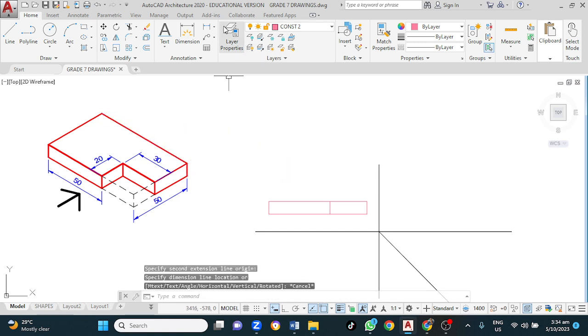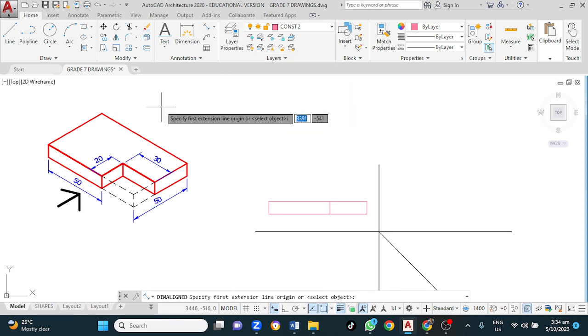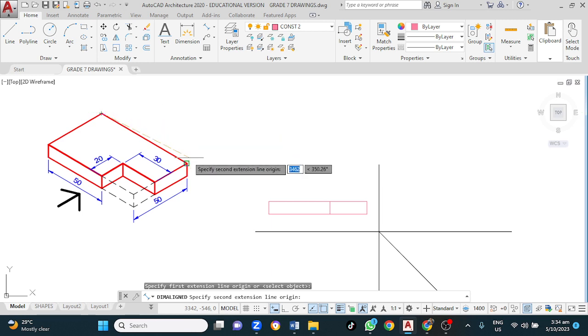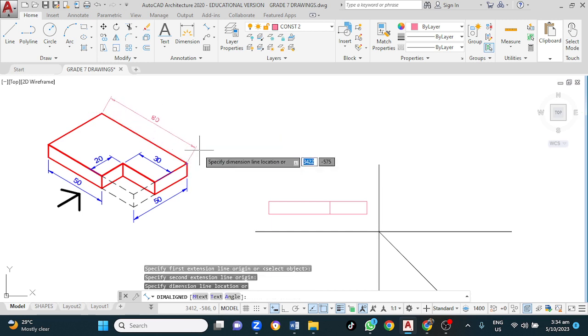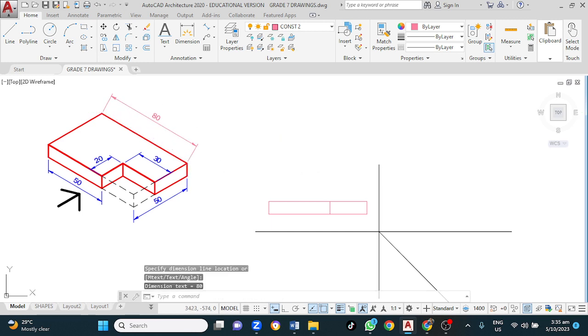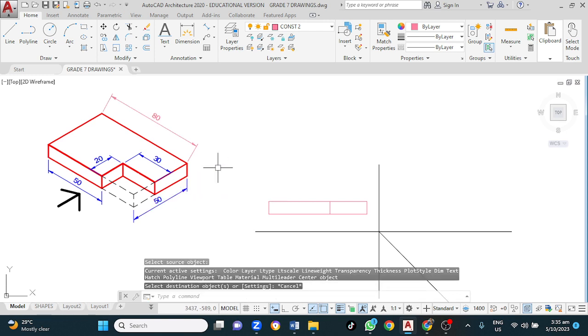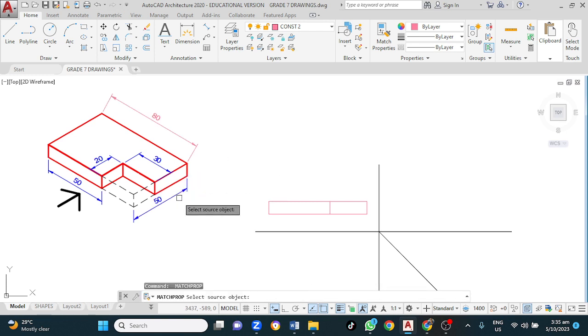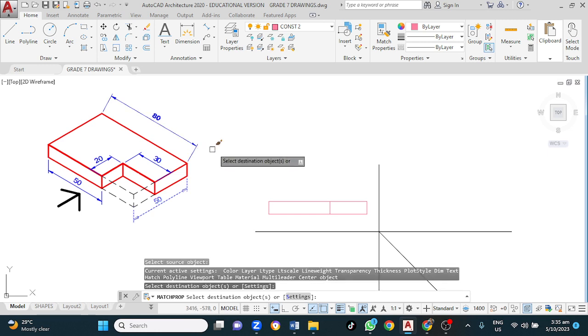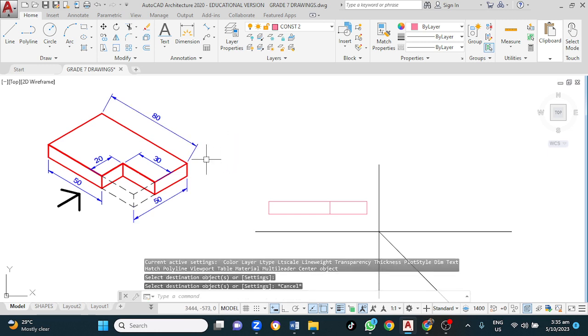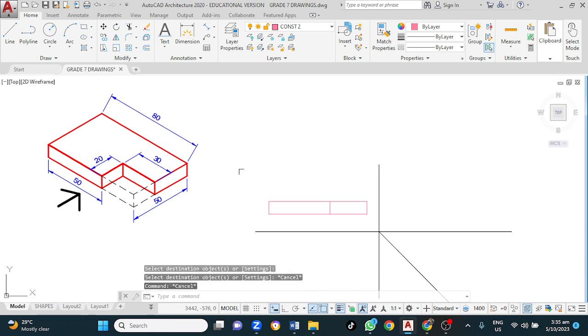No, I should use a line. Left click here, left click there. To change the color, I need to type MA, enter, left click, oh sorry, spacebar, click this, then click that, escape. I want this to be aligned, well, it doesn't really matter how we make it.